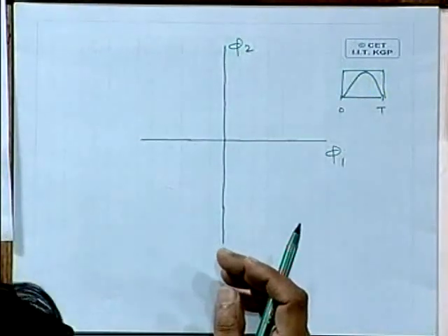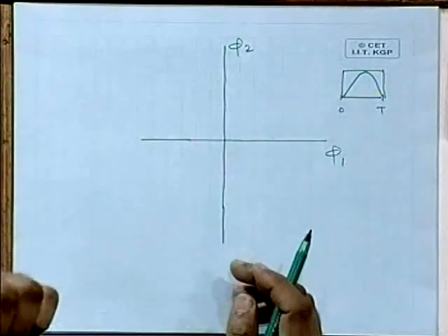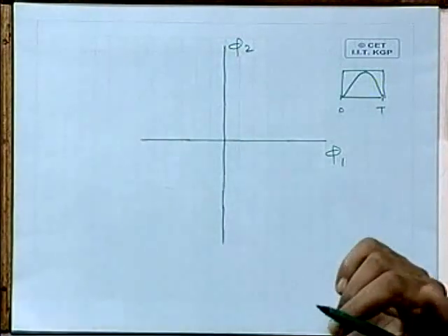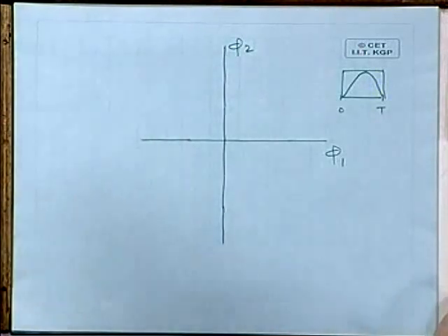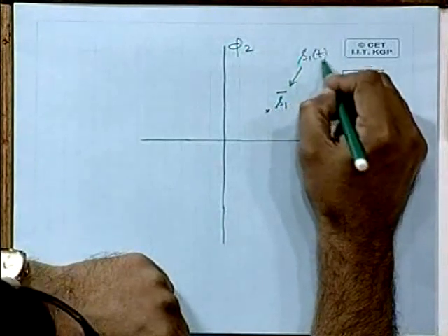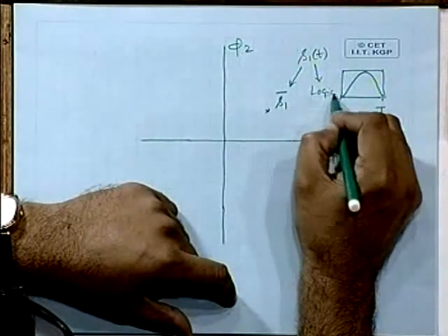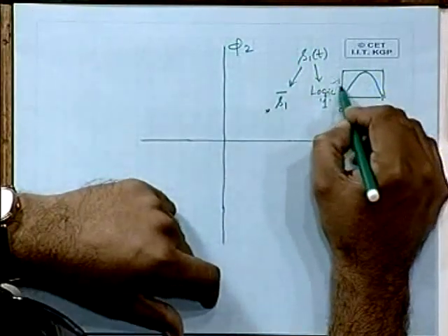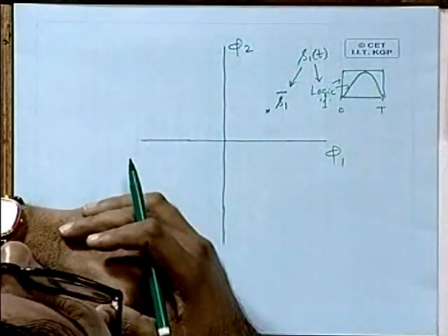Now, just to give you a quick example of how much we can understand about the modulation scheme, let me say that I have two signals to transmit, a very simple scheme, corresponding to the binary sequence, where I am visualizing that one bit is equivalent to one symbol. Because there are two bits, 0 and 1, I need two symbols, and hence I need two signals S1(t) and S2(t) to be defined. Now I am falling back on my signal space description, and let me say that one point is here. I am calling this the S1 vector, which corresponds to S1(t), one symbol, which may correspond to your logic 1, which may be looking like this or anything else.